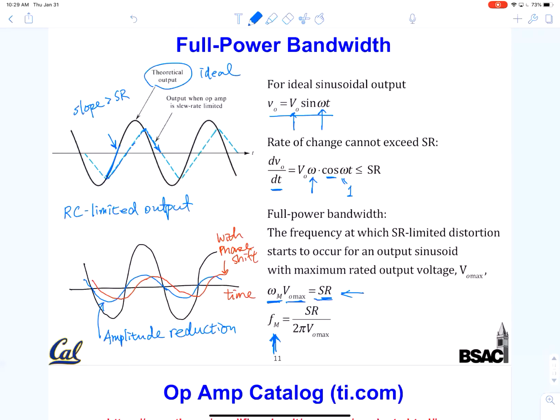There are generations of different technology. The very old op-amps use older technology that may have higher capacitance, larger features. And remember the first op-amp was designed in the 70s. So now it's almost 4 or 5 decades later. The technology has become a lot better. So certainly there are better technologies that can give you overall higher gain bandwidth product. But there is still a physical limit that will force you to do the trade-off. Any other question?